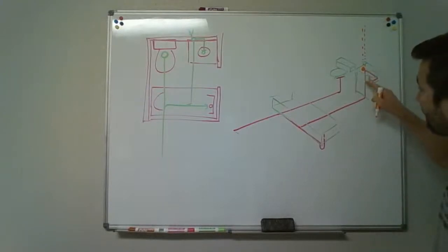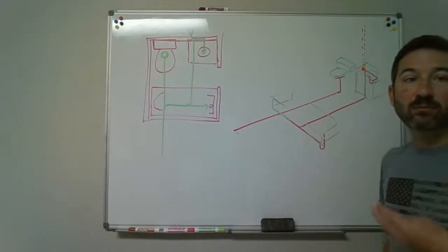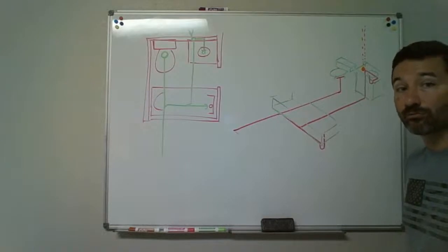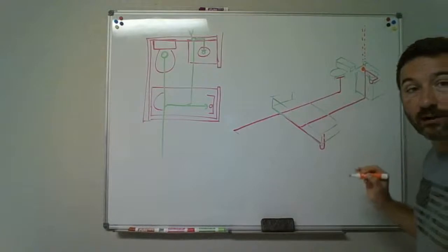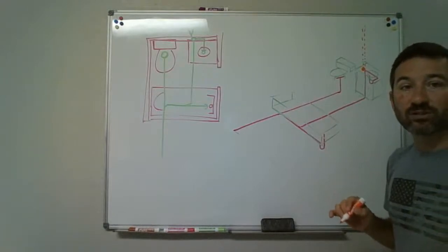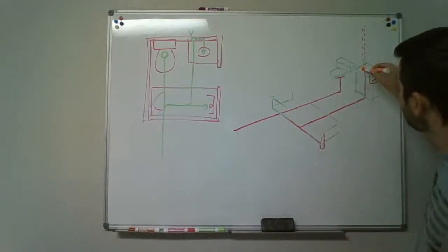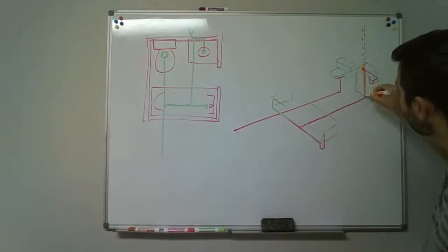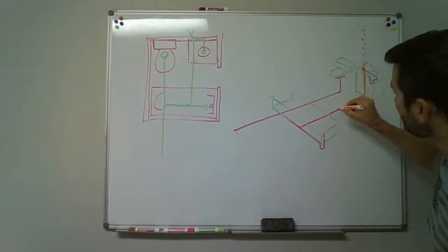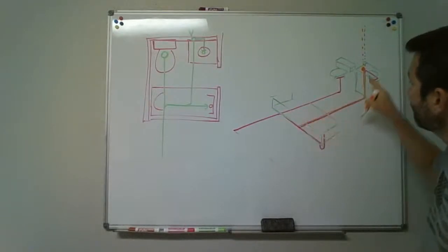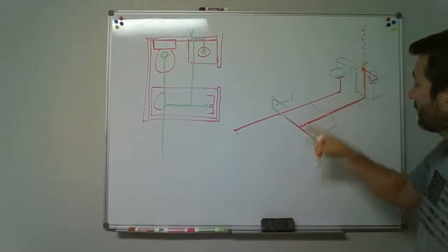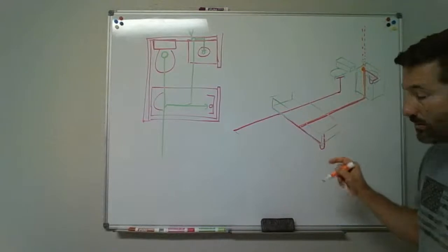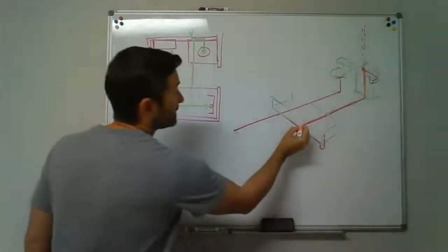It's wet because the lavatory is draining down, but some other plumbing fixture is trying to pull air through the line. And it says continue it from there to the most downstream fixture that's utilizing that vent. So we're going to start to flow and highlight over this to show that part. This all is wet vent. It's wet from the sink, but through that line, the toilet and the shower are trying to pull air through there. We're going to continue on downstream.